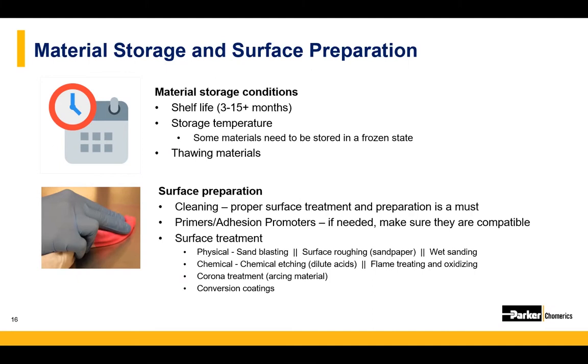But if you did your homework and you've received your frozen material, then you would now need to defrost it, and you can either do that at room temperature or in a warm water bath to bring that temperature up to which they can be worked. At the same time, while your compound is defrosting, the substrate may need to be prepped so that the materials adhere well for both mechanical and electrical properties. Some materials will need primers or adhesion promoters to prepare the surface and make sure that the compounds stick well.